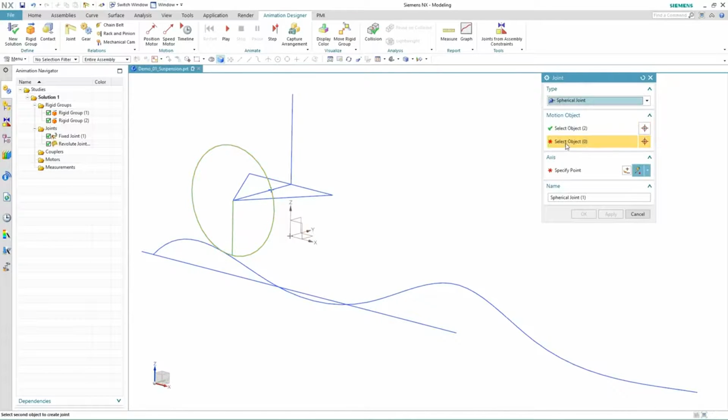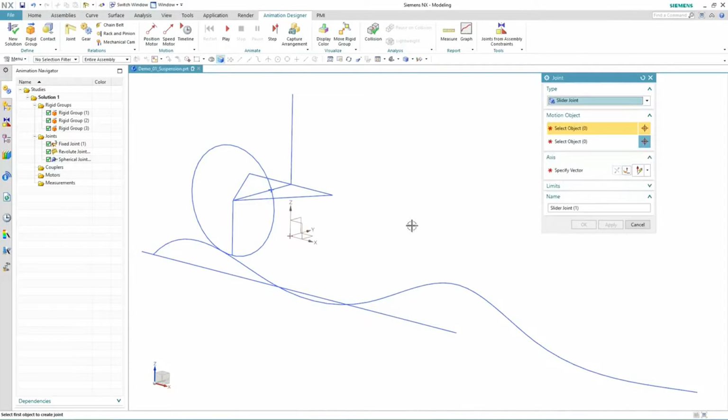We only have to define the joint, but other operations such as rigid group creation are done automatically. Rigid groups tell the system what can move but are being created during joint definition. This automated approach is perfect when defining the motion of a small assembly.